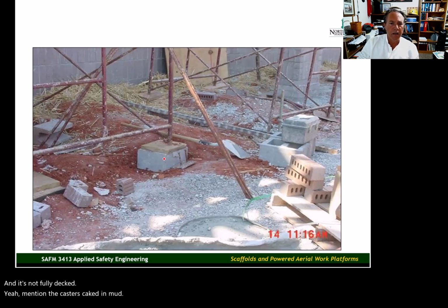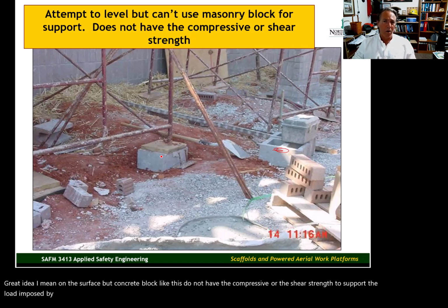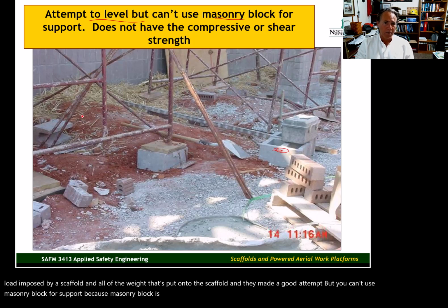Here they are using a concrete block like this to keep their scaffolds from sinking into the mud. Great idea, I mean, on the surface, but concrete blocks like this do not have the compressive or the shear strength to support the load imposed by a scaffold and all of the weight that's put onto the scaffold. They made a good attempt, but you can't use masonry block for support, because masonry block is not generally going to be rated to carry any kind of loads.